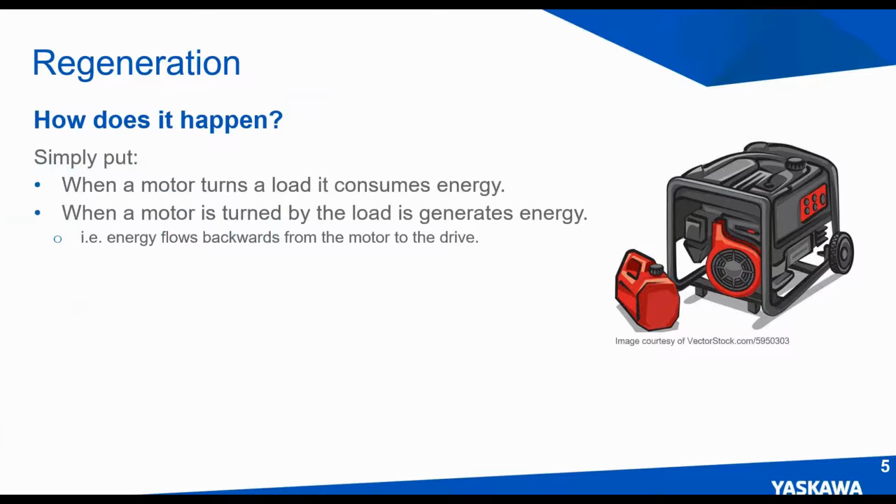Think of another person trying to open a door, but you're resisting them. They are doing all the work, you're just holding back. Your holdback is that regen energy. This energy flows back to the motor and into the drive, and the drive needs to do something with it. But when does that happen?